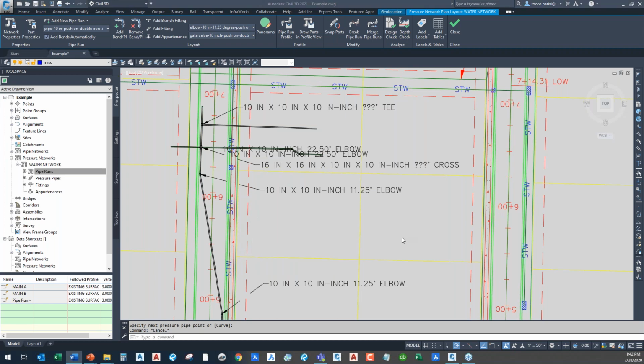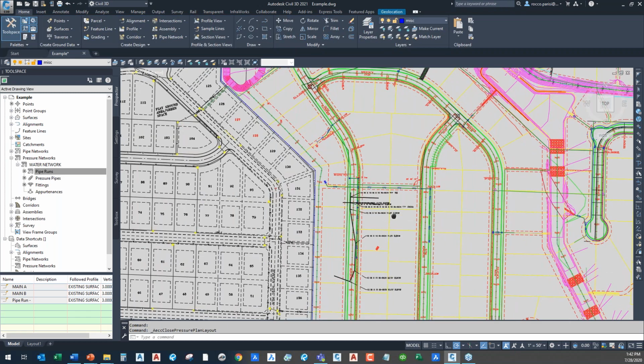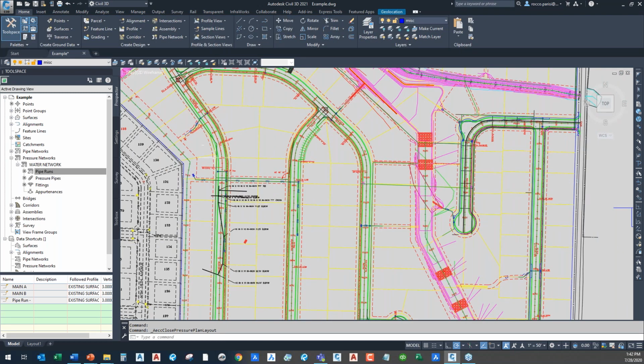All right, now other items that we've done in the 2021. They've integrated Infraworks, Revit, and Civil 3D together in terms of roadway corridors. Now, I'm not going to show you a full-blown setup here because it really does involve the idea. Let's just explain the idea, right? The idea here is that in 2021, what we can do is we can take any roadway corridor that we've designed, we can export it out to Infraworks. It will build that corridor in Infraworks for us.